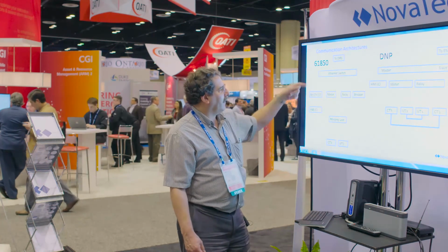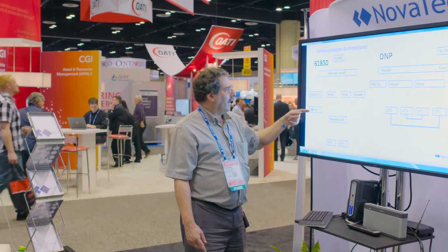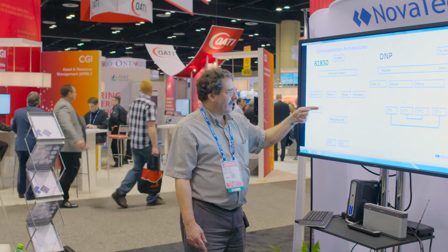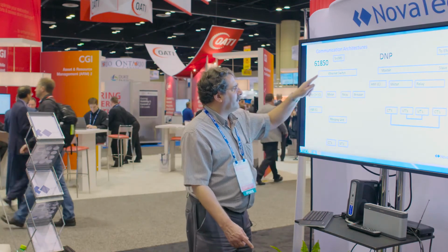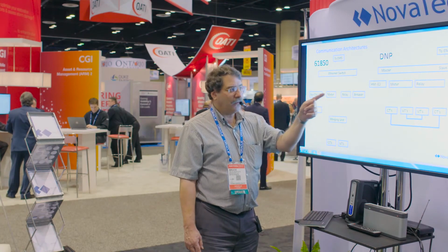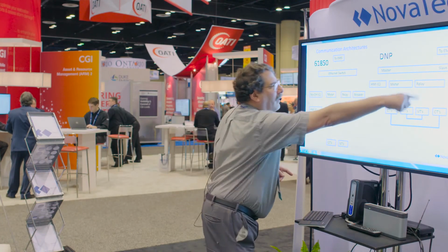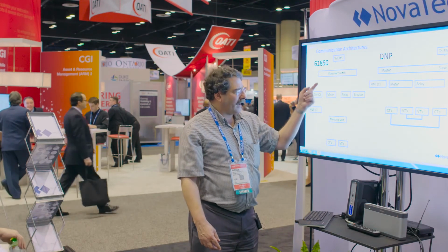Also, you can simply hang off the system controllers that you have, for example an Orion, or you can hang off an HMI. Again, that could be another Orion. But the key is that all these devices share all the information without explicit links. The explicit wiring is all gone. See all this wiring? All that stuff's gone. You just have this wiring, and all the other information is traveling through the Ethernet.